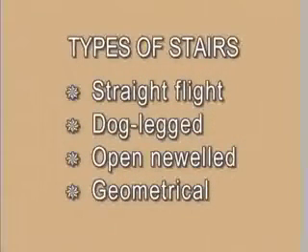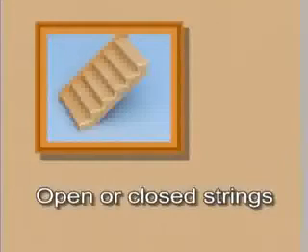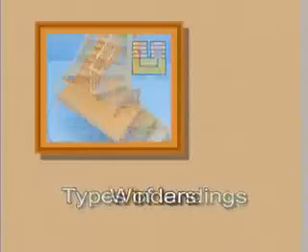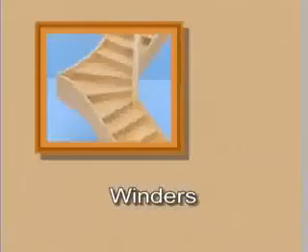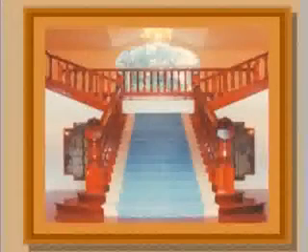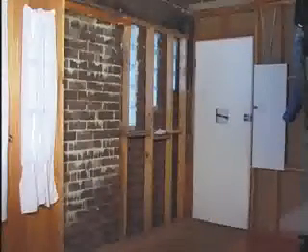As well as being defined by their construction methods, stairs can be further described by the types of strings, the number of turns, the types of landings, and the use of winders. A description of this staircase would be an open-newelled closed string stair with 2 quarter-turn side flights.